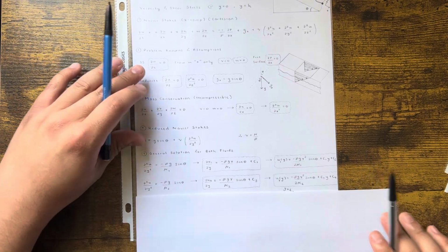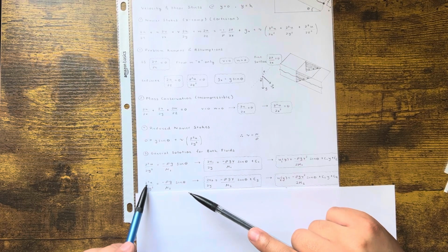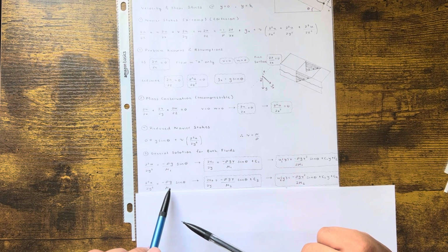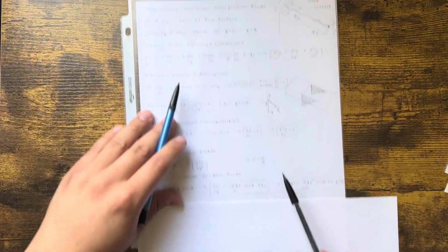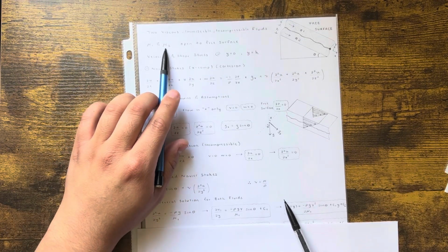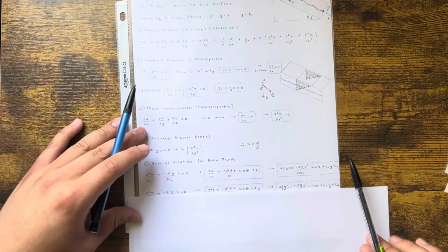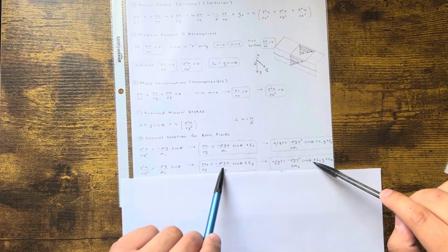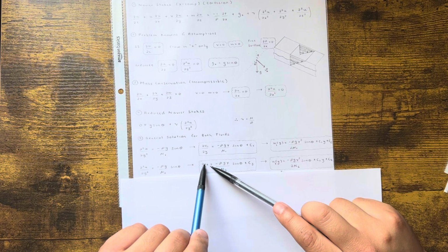And two fluids, so same thing for the other one. All that changes is the mu2 right here. That dynamic viscosity is just different. That's what the problem's saying. I mean, we said it here: mu1 and mu2, separate viscosities, and it's open to the free surface, all that good stuff. So this is where we're at. The only thing that's different between these is the mu2, the velocity 2, obviously. Different velocity profiles.